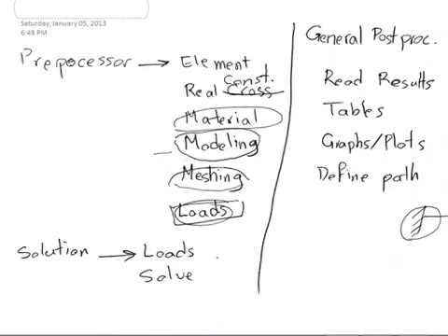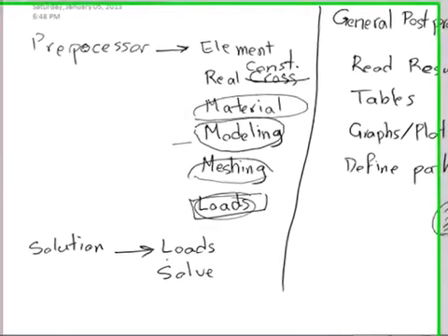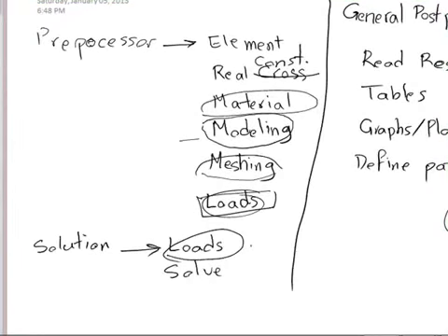And then, as I said, in the solution step in ANSYS, you can also define loads. This is basically the same thing. You can change loads in either of these two steps, either in the preprocessor step or the solution step. And there is the solve sub-step in the solution step, that when you go through there, you can start solving the model and analysis that you have just made in ANSYS.